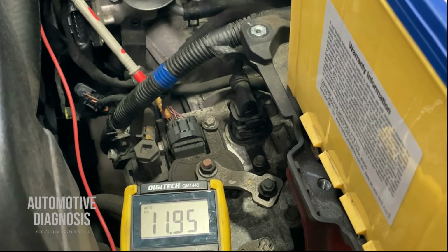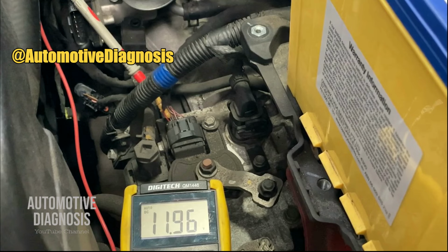So if you are testing the output signals, because we are checking directly on the range switch, if you're checking the output signal in any step and you see one or more signals are not exactly the same as the specification inside the workshop manual, it means the range switch itself is faulty. Of course, before that, you need to make sure the connector itself is okay as well. There is no dirt, moisture, or corrosion inside the connector, because you want to make sure your reading is accurate. So if the output signal over here is not okay, you have to replace the transmission range switch.